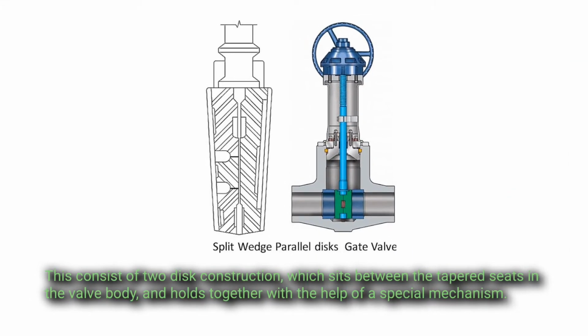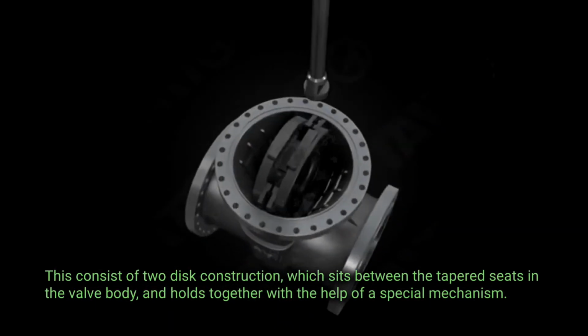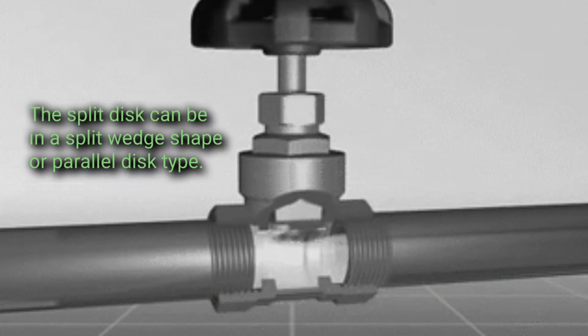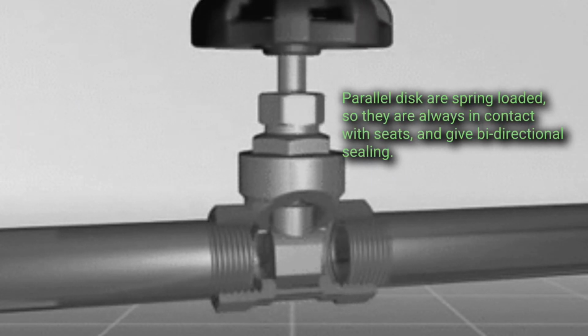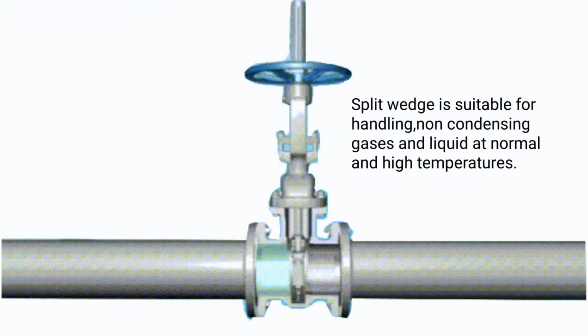Split wedge or parallel disc gate. This consists of a two-disc construction, which sits between the tapered seats in the valve body and is held together with the help of a special mechanism. The split disc can be in a split wedge shape or parallel disc type. Parallel disc types are spring-loaded, so they are always in contact with the seats and give bi-directional sealing. Split wedge is suitable for handling non-condensing gases and liquid at normal and high temperature.